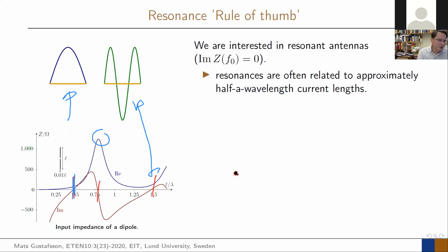Okay, so I continue with these cases. When we design these antennas, we also would like to have them in some ways as simple as possible and as small as possible. And that means that dipoles are really in the majority of cases sitting down there. That is what we go for when we can. So we make them half a wavelength long or approximately half a wavelength long. We have a nice current shape on them, nice radiation properties that we saw last time. So that's where we try to do the antennas.